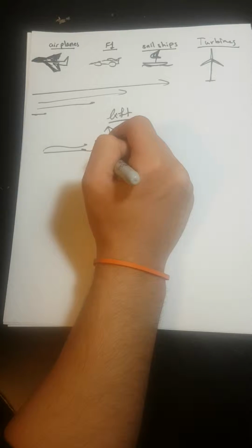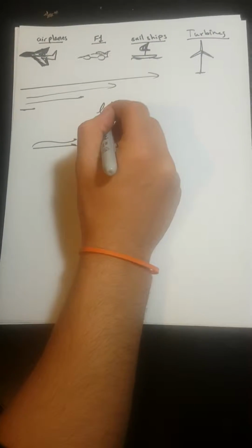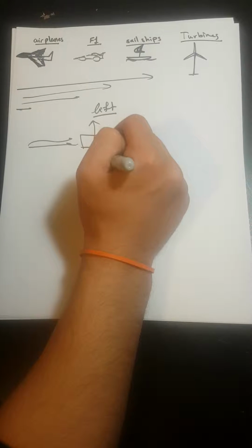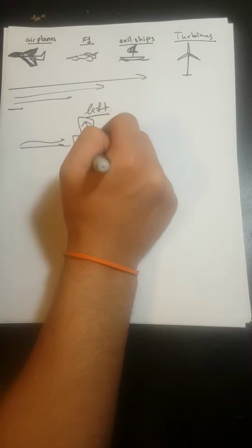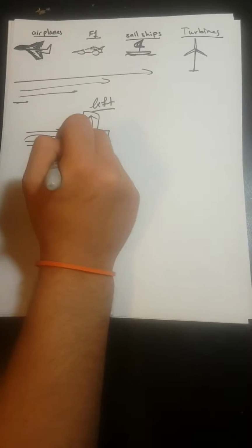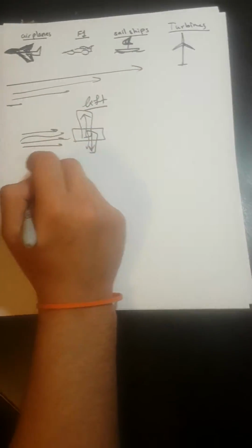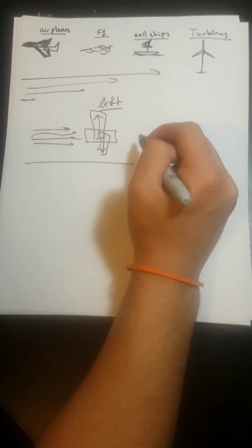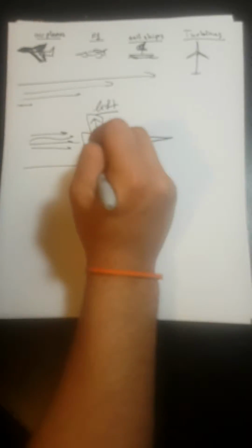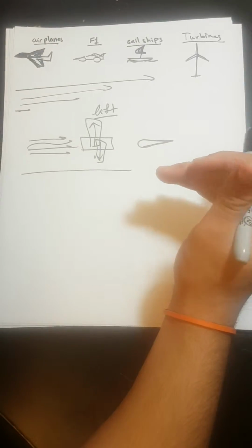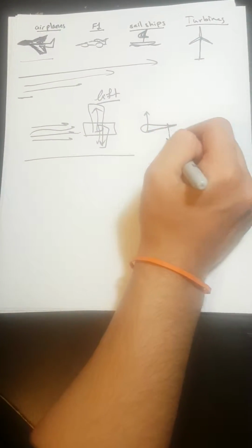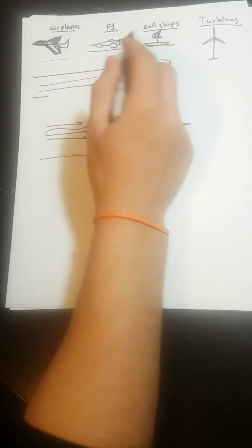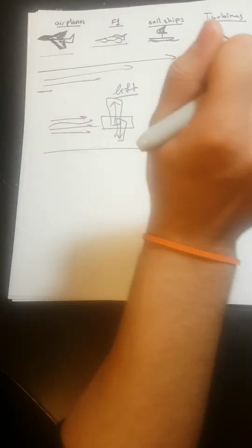Depending on the shape of the solid body, the direction of the lift force would actually be generated. It could be an upward force or a negative force, but the direction is always perpendicular to the angle of attack of the incoming air velocity. Because of this, not any solid body would generate useful lift. Either it's upward, as in the case of airplanes, or downwards when we optimize it in Formula 1 cars to cause grip and handling for corners and sharp turns.